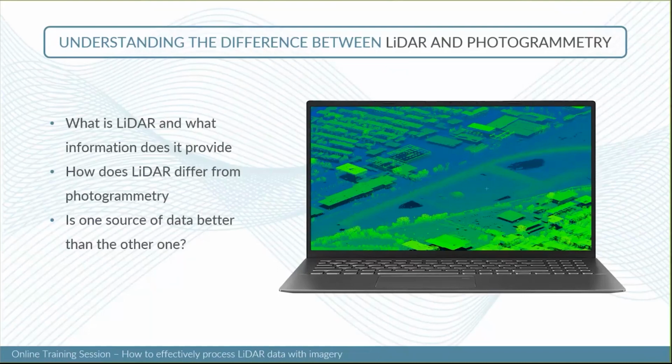The post processing could be quite long if you have a big amount of data to process. Once you have all your images, you need to do your aerial triangulation, tie all your images together, have a nice bundle block adjustment. Then you need to perform dense image matching, which could be hardware consuming. It sometimes requires good hardware to process such big projects.